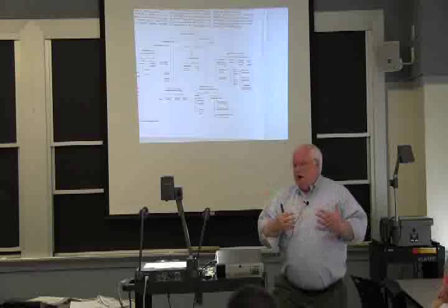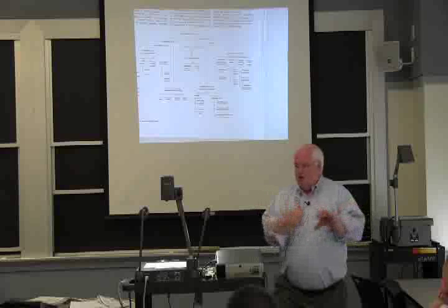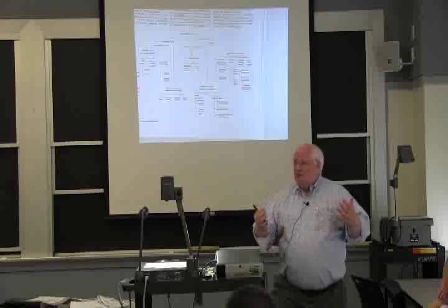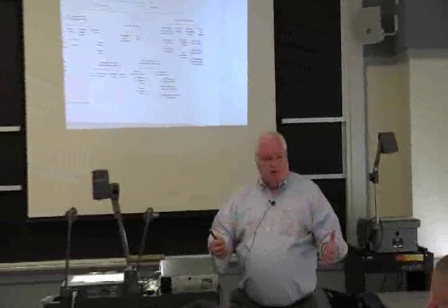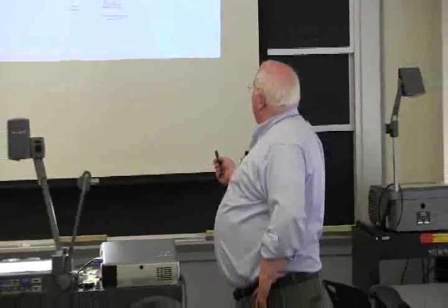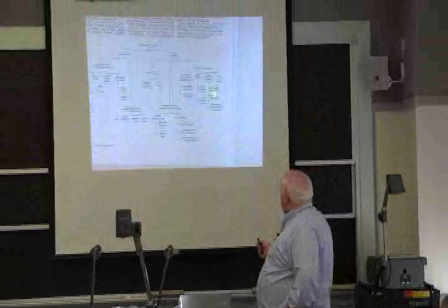And the problem in die casting is your cycle time. You've got to push it in and hold the pressure on there until the thing solidifies. The bigger the part, the longer it takes to extract the heat of fusion. If you've already gotten half the heat of fusion out, you can cut your cycle time down by half. So they look at high pressure die casting, and there's this whole technology of rheocasting.